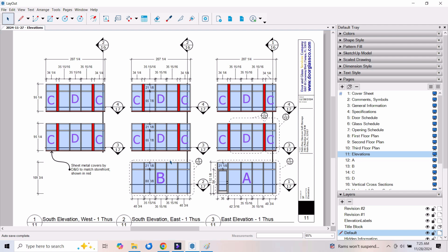That's not something which is just going to happen. The standard practice for installation is to install a frame relative to the opening. So you want to put a single frame in an opening, get the frame centered left to right, top to bottom. You have the different standard shim space deductions. That's what we train our installers to do.